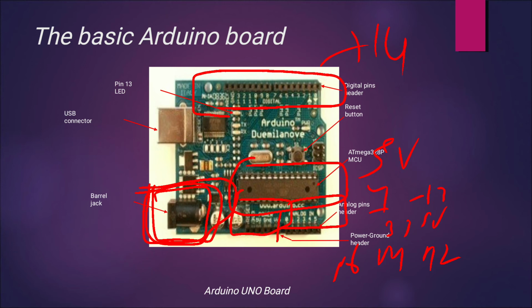It can operate on external supply of 7 to 12 volt. Power can be applied externally through the pin VIN or by giving voltage reference through the IO pin.